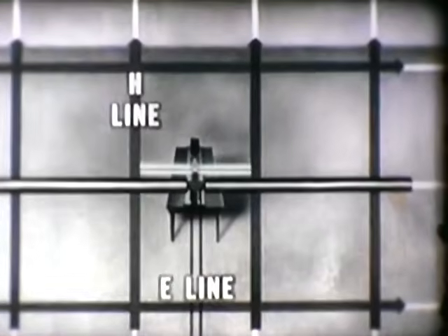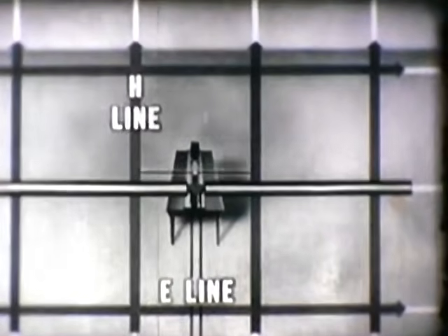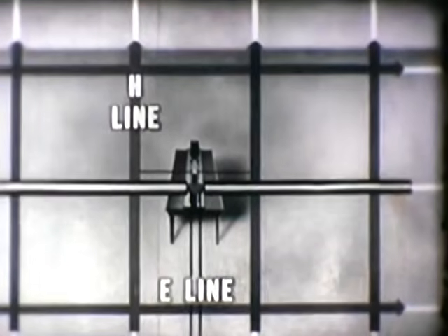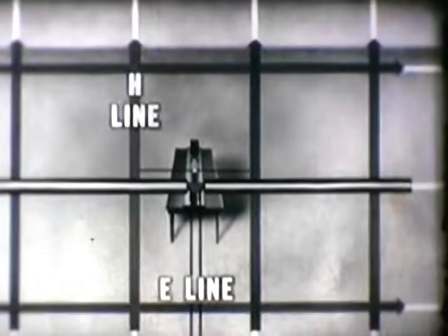The transmitting and receiving antennas are now parallel and broadside to each other. This broadside position is necessary because of the nature of the radiation pattern of the half-wave antenna. The shape of this pattern indicates areas of no radiation or nulls along the axis of the antenna.